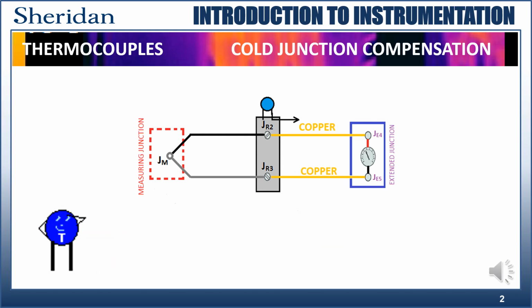Yes, a thermistor. We know that they can act as a thermal switch, but we can also monitor its change in resistance and use that to calculate the temperature of the J2 and J3 junctions. We simply put the thermistor in the isothermic block, and it will measure the temperature. Hooray for Mr. Thermistor!